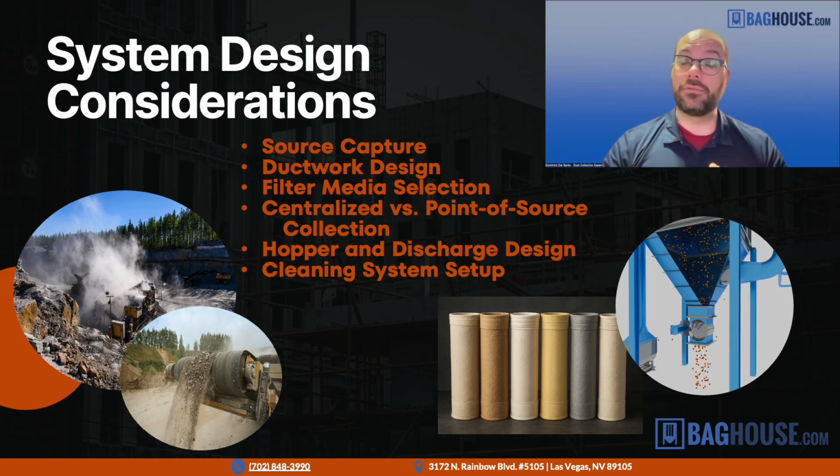We talked a little bit about filter media selection. In general, we want to make sure we're selecting the best filter media based on the temperature, but then also if there's things like moisture to take into account, other chemicals in the gas, also the particle size and the dust loading that the system sees. All of these play into what kind of media we select.